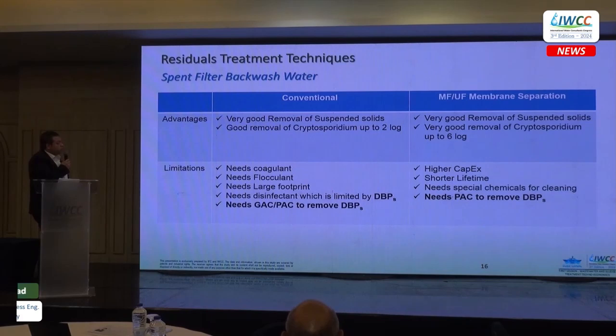This is a comparison of treatment techniques for spent filter backwash water. We have to weigh whether to treat them conventionally or using membrane separation. Both of them have advantages and limitations. We could see that both can remove suspended solids very well, but the conventional technique has limited removal efficiency for Cryptosporidium, while ultrafiltration has very high removal efficiency, up to 6 log for Cryptosporidium. And both of them will need granular activated carbon or powder activated carbon to remove disinfection byproducts.